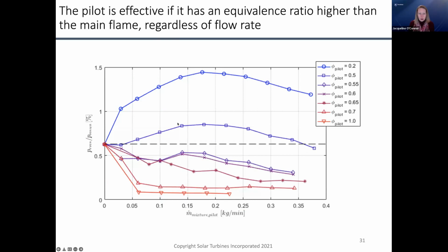And so based on the fact that we get really good suppression out of very small flow rates, we do think it's a thermal effect more than a fluid mechanic effect, but you're right, there would be some change in shear layer response due to that sort of secondary pathway could be possible too.